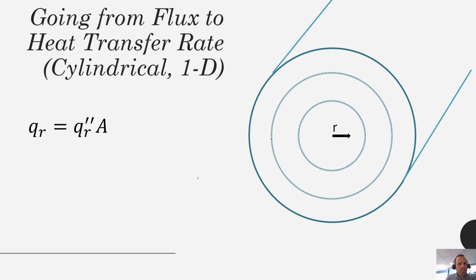This gets a little bit trickier with radial systems. Let's say that we have some kind of heat flux going out from here. So we have q_r flux going out from the center, out radially in all directions. What's tricky here is, let's say you have some kind of heat source in here, well, that heat's going to escape, so that same amount of heat is getting from here to somewhere outside the pipe. So the total rate of heat transfer leaving from here out to here is going to be constant.